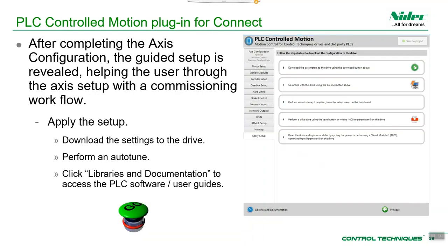Okay, and that's it. At the end of that setup, you would then apply that, download the settings to the drive, perform an auto tune, and then you'd move over to setting up the PLC side.